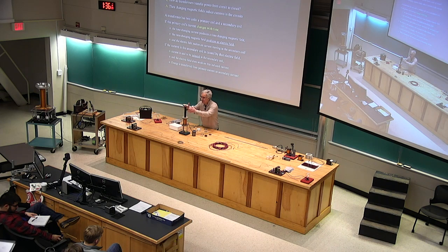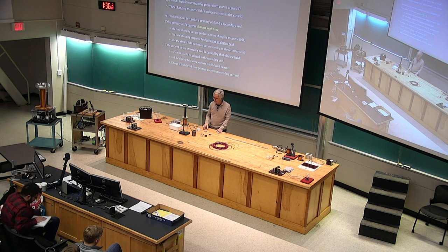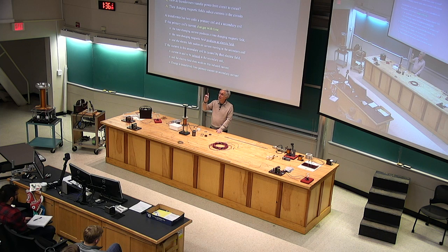Okay? So the details of why this guy jumps, a little complicated, but the basic idea is this thing creates a fluctuating magnetic field, north, south, north, south, north, south, and that produces an electric field, drives current through this wire, which is just a ring, and it becomes magnetic, and the two of them repel each other. If instead of using a single ring like this where you can't really see the current, all you can see is the magnetic influence of one on the other, we can switch over to this, which is a second coil of wire with a light bulb as part of the circuit.